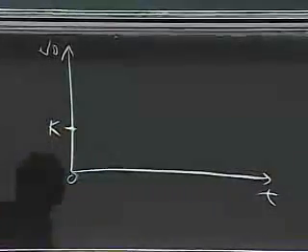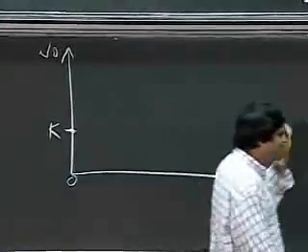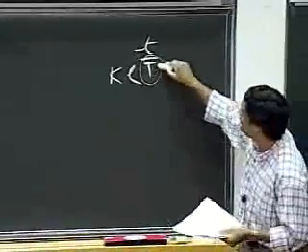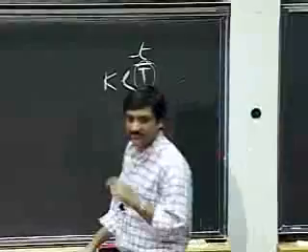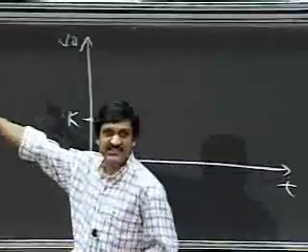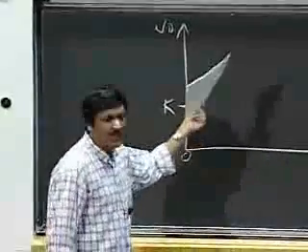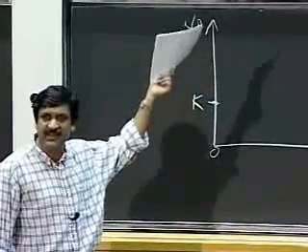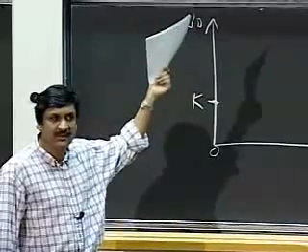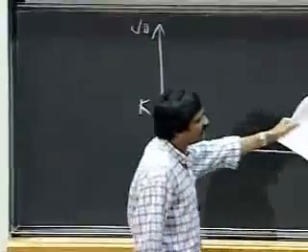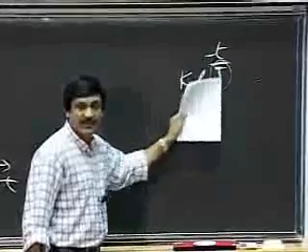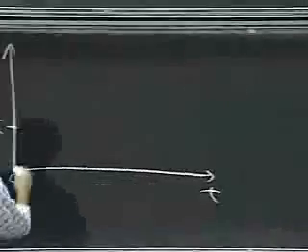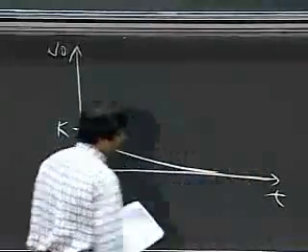Here's where the interesting stuff comes in. The final value on the capacitor depends a lot on whether T is positive or negative. In the very simple RC circuit we looked at, what was capital T? What is the time constant? RC. So this was a positive quantity. So when capital T is positive, my output is going to look like this.